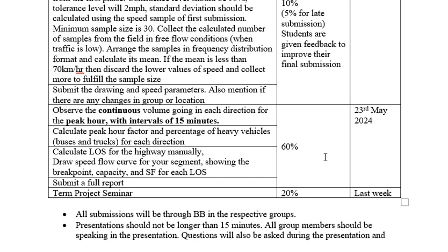But again, there are some requirements. So I would advise you to wait till I tell you the requirements. If you want to do it, at least ask me what we should do. But the data should be collected in the peak hour. You have to calculate the peak hour factor and percentage of heavy vehicles, and you need it for both directions. This is the item you need from the field, and then you will do some calculations for the level of service of the highway. You will plot some graphs.